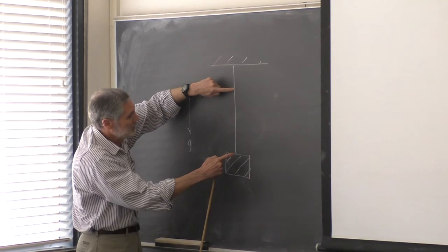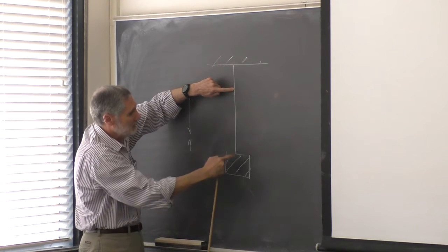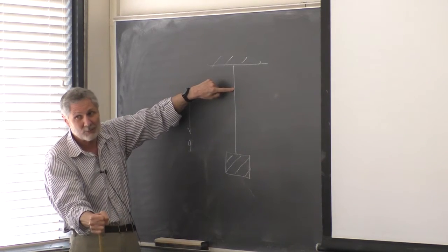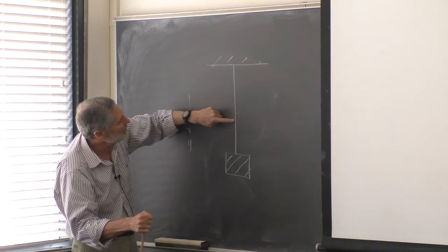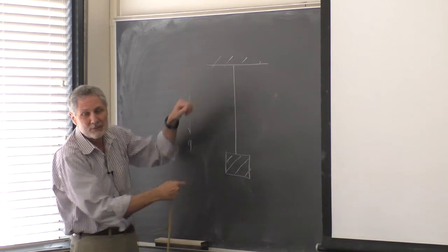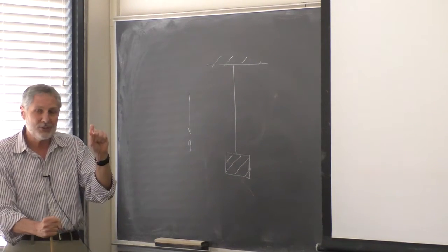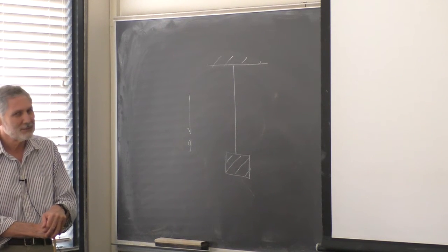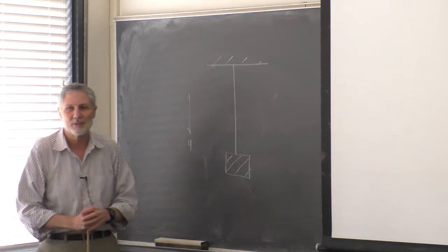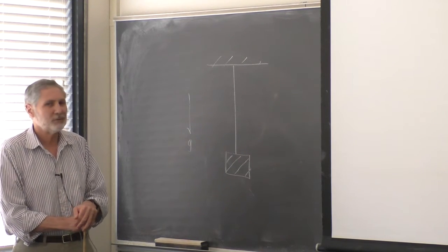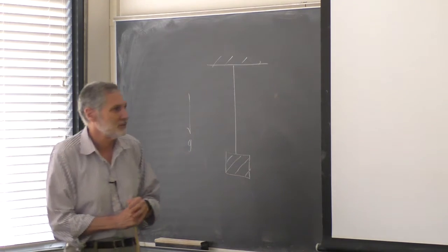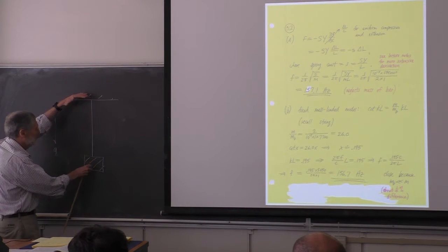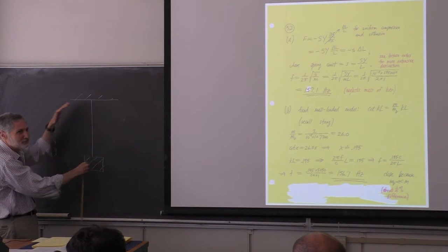And it's the weight of not just the mass, but the weight of the wire, which is a small effect, but still, we said exact, right? We're talking about an exact solution here. And as you go higher and higher up, you have to support more and more mass. So it'll be straining more in equilibrium. So we've got non-uniform strain here. This is a little bit of a problem, but it can be solved. I've solved it before. Okay, but anyway, let's look at our model here, where we're taking this in our usual case, making it horizontal.